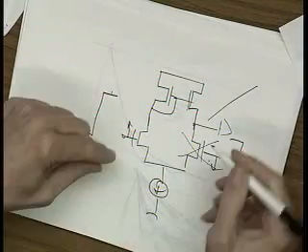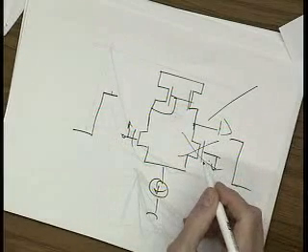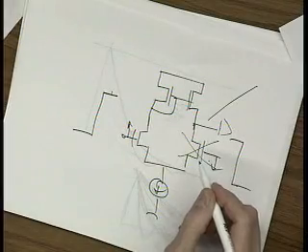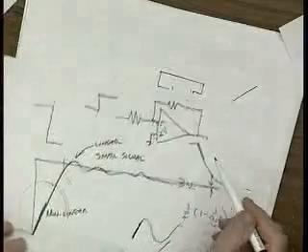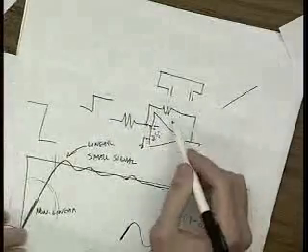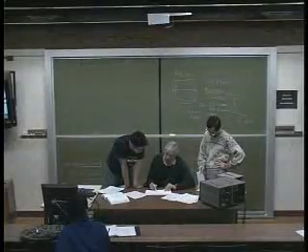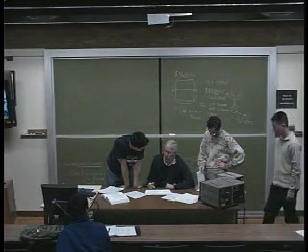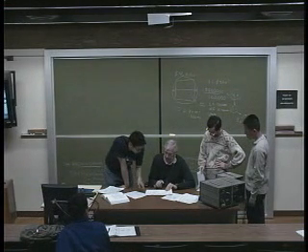Then what happens? Finally, the feedback comes around. The circuit's in feedback, right? So we have to have feedback in our circuit. Absolutely. We can't do it without the feedback. You've got to have the feedback. The circuit won't work, right? If you don't have feedback, if I do this, minus plus, I put a big step on here, no feedback, this thing will just stay saturated, right? There's nothing. So it'll just keep going like this forever.